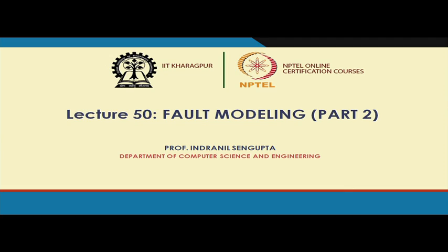So, we continue with our discussion on fault modeling. You recall in our last lecture we talked about some fault models at the behavioral level, functional level and also the structural level. We mentioned at the structural level the stuck-at fault models are the most commonly used, and also the bridging fault model is quite common in modern day VLSI chips where the wires are very close together.